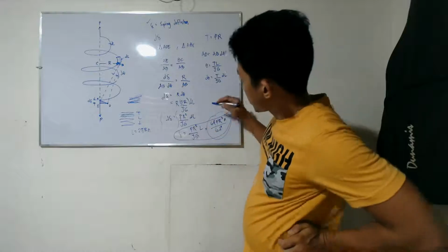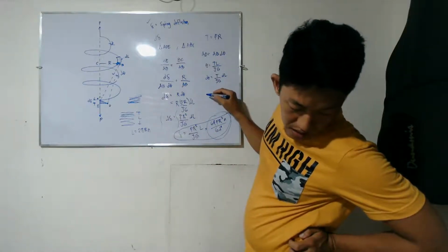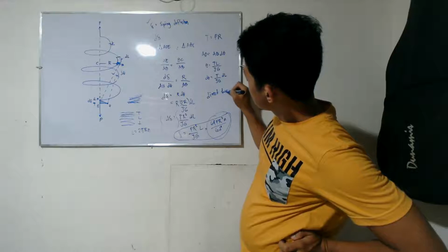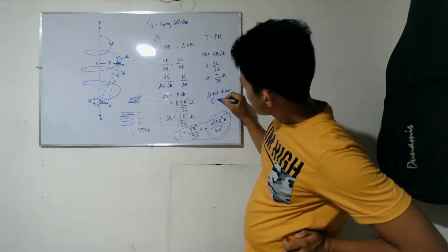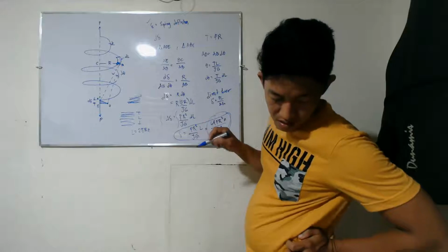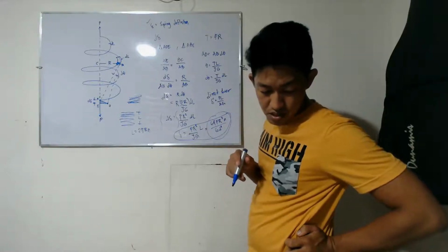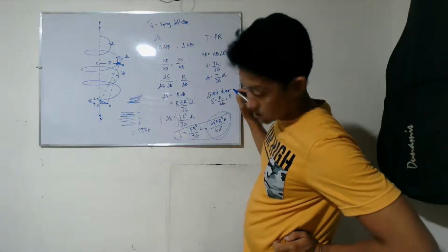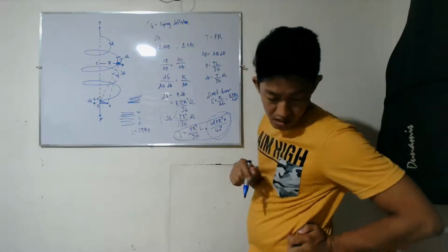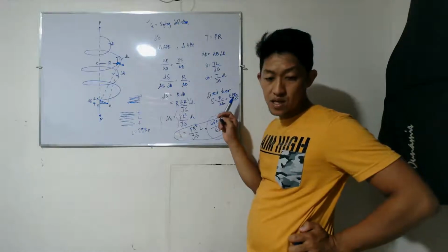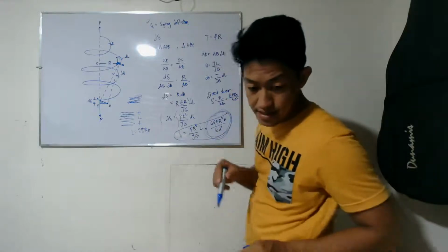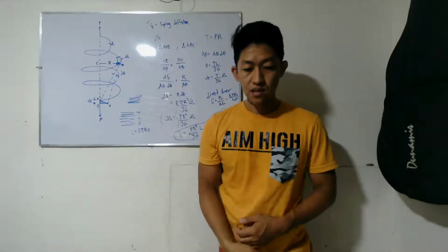Anyway, the deformation caused by direct shear is δ prime equals PL over AG, which is equal to 8PRN over Gd squared. So you add this one. But usually it is negligible, so we use the earlier one. But we just show this here.